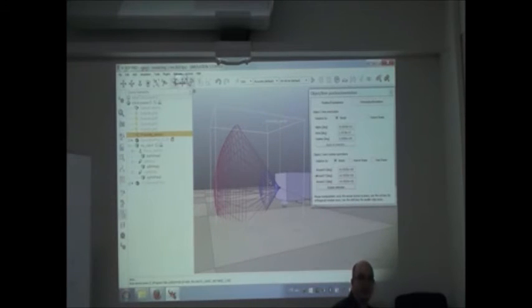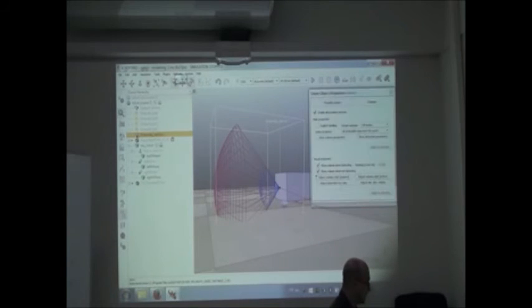Now you can see that with this configuration, the red zone is the detecting point. Do you think that with this configuration we will be able to use it as a sensor? I mean, that's not going to work, because we're going to detect an obstacle which is the ground all the time. If we put a sonar that is looking like that, we detect the ground. We don't want that. So we have to change the type of sonar we want. To do that, you double click on the icon of the sonar. Here.